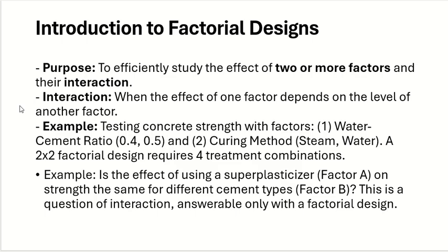For example, concrete strength. I'm using 3 methods of curing, and I test the concrete after 3 days. You test after 3 days, and how many days then? 7 days. 28 days. Now you know that strength at 7 days is not the same as strength at 28 days, right? Yes, they are not the same.